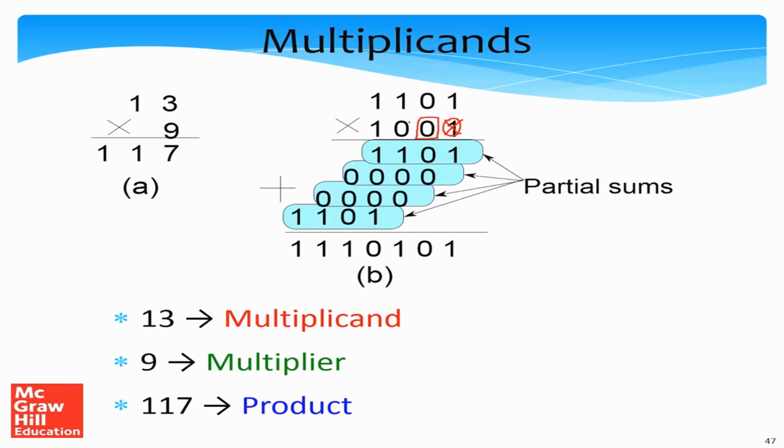We again shift 1 step right. So this bit becomes the least significant bit. Since this is 0 also, we don't do anything till we come to the last position. We'll not discuss what we do in the case of the last position because this varies for signed and unsigned operands. But the important point to note from this diagram is that if the bit under consideration in the multiplier is 0, then we don't do anything. In a sense, we don't update the partial product.